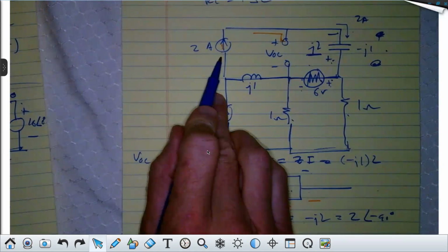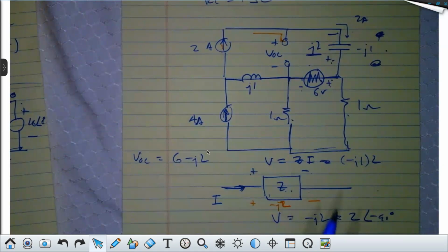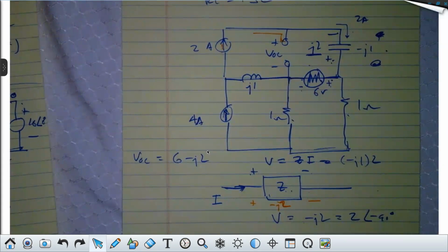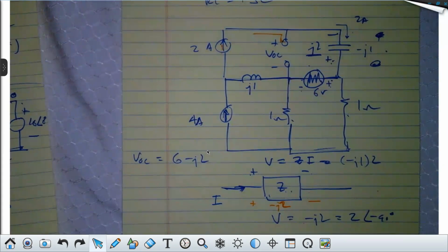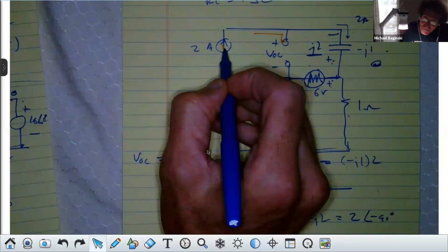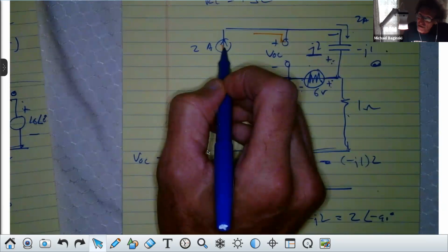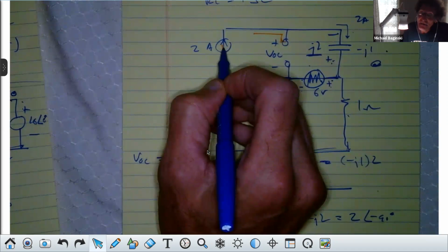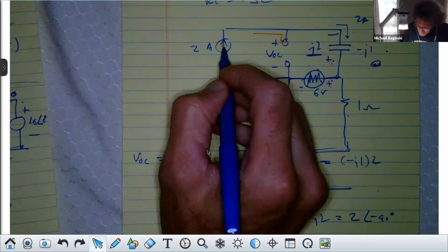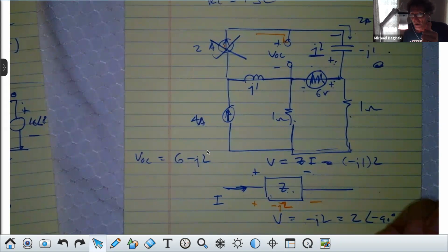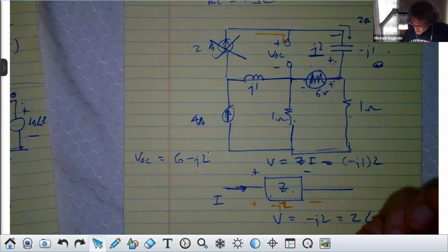It's a short circuit. What's the other option? Open circuit. Yeah, when I say turn it off, think about it. If current goes to zero, only if you take the element out, right? It's an infinite impedance or an open circuit, right? Literally, this isn't there. You with me? Okay, you turn them off. Current sources become open circuits.